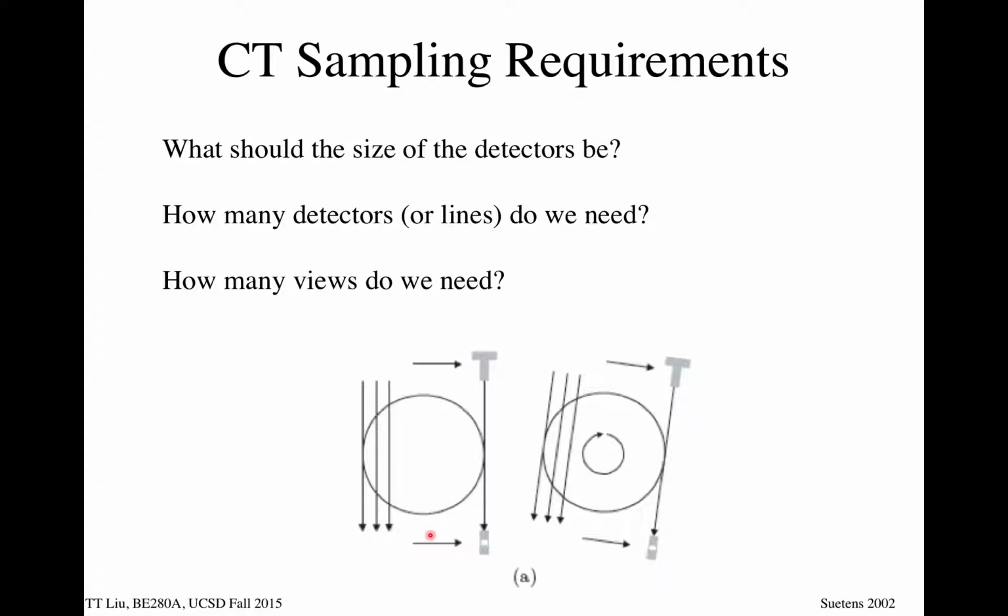Anybody have a feel for what would make for a higher or lower resolution as I'm taking my detector along this way? Well, we can sample, let's say we sample every 50 microns, so that's a really high sampling rate, right? We're going to stop every 50 microns, take a measurement, stop every 50, like that. So that's one thing. What else could affect it? Say it. The size of each detector? Right. In this case, we have one detector. So just like the size of that detector.